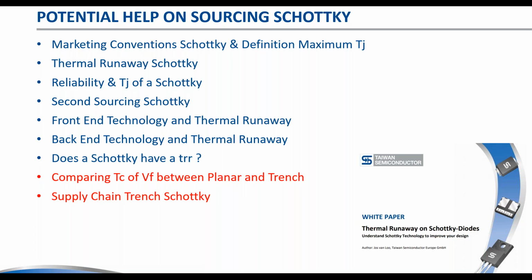So, second sourcing Schottky is becoming quite complex, and search engines do not help here to catch the diversity of a Schottky. So in the case of a Schottky diode, you still need to look at the datasheets and not rely on search engines to get an equivalent.